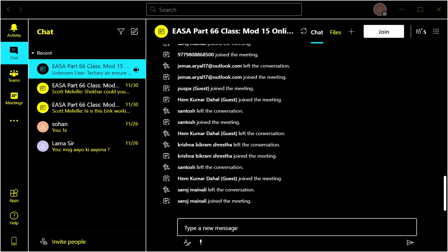Engine oil is very clear. So if you put brand new oil in, it's very hard to see it sometimes. And once it gets used, the colour will change, it will get a bit darker, it makes it a bit easier to see. So that's why it made it a bit awkward initially. But again, if you overfill an oil tank as well, that can cause problems. That can cause siphoning effects. So make sure, depending on the aircraft you're working on, it will tell you only top the oil up when it's hot, maybe after 5 minutes of engine cool down.